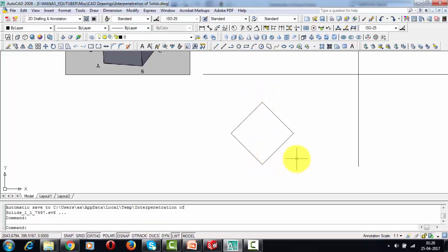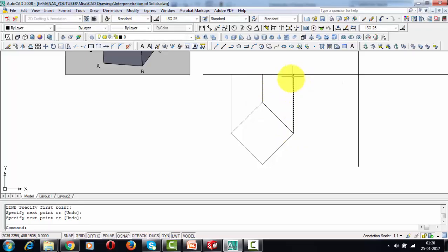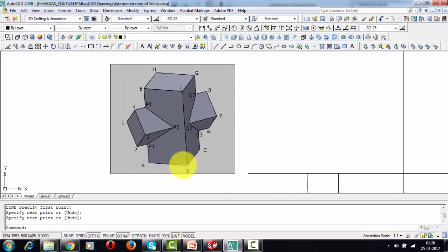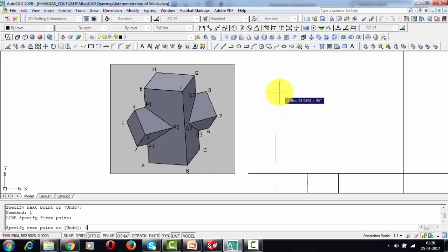Okay, so this is how the object looks from the top. All right, now we're going to look at this from the front, and for that I'm going to be projecting these lines from the bottom like this. Now this vertical prism in fact is having a height, we are assuming that height to be equal to 100 millimeters. So what I'm going to be doing is I'm going to go 100 millimeters above, something like this, and that's it.